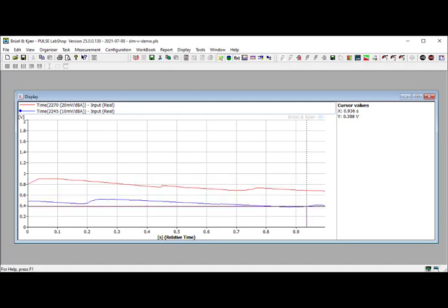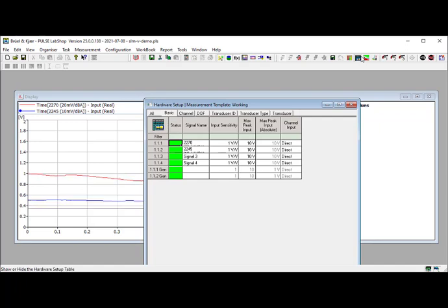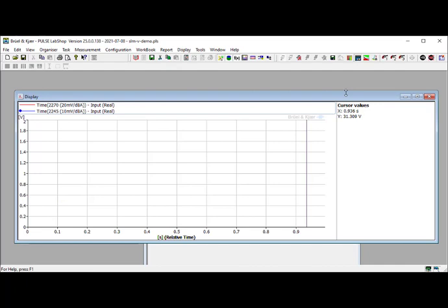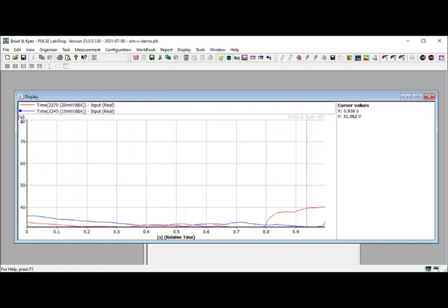Just having the voltage level isn't terribly useful, however, so a quick adjustment to define the sensitivity of each channel, 20 millivolts per dBA for 2250 and 10 for 2245. And we now have signals reflecting the actual dBA of each signal.